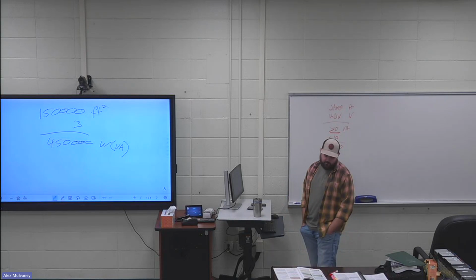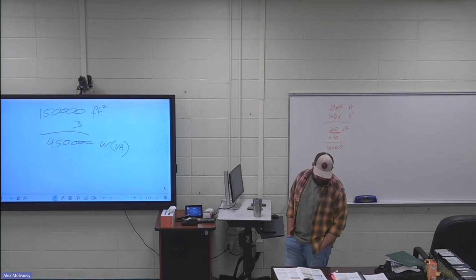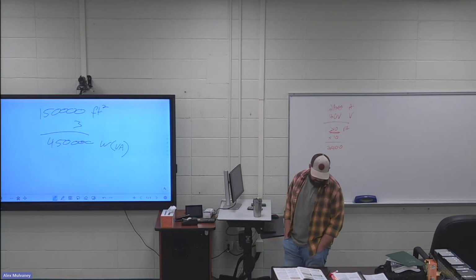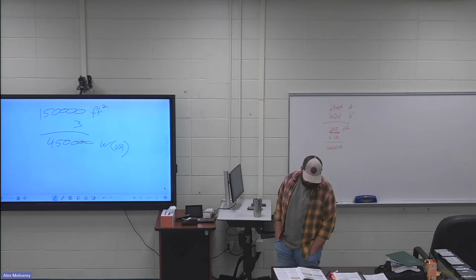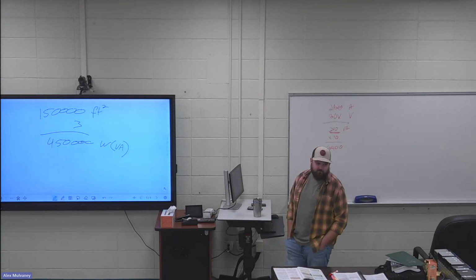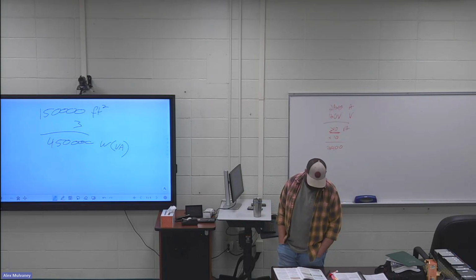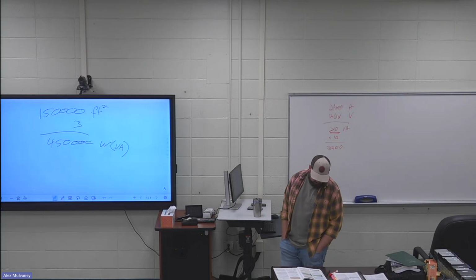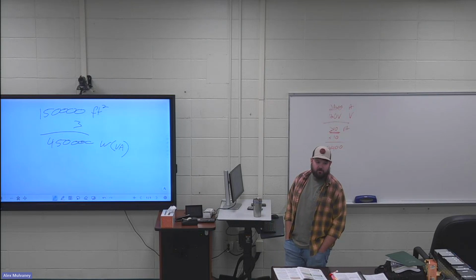Branch circuits may supply non-continuous loads, continuous loads, or a combination of 2 per NEC section 210.20(A). The branch circuit rating shall not be less than the non-continuous load plus 125% of the continuous load. A continuous load is defined by NEC Article 100 as a load whose maximum current is expected to continue for 3 hours or more.